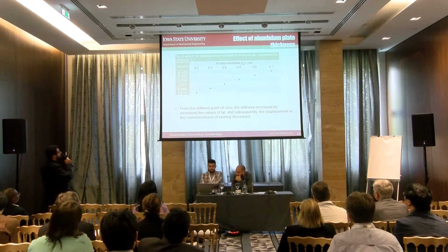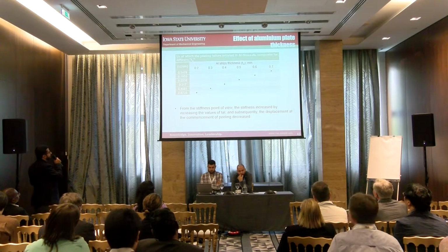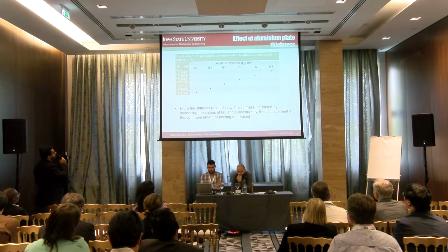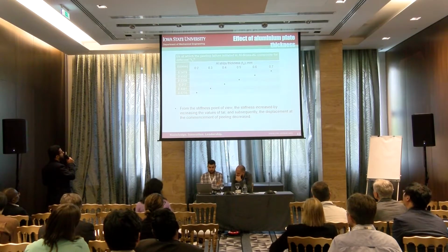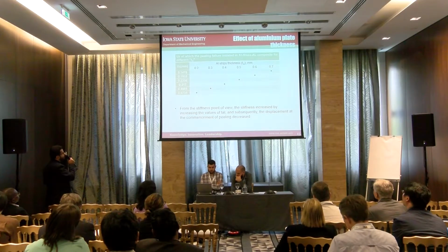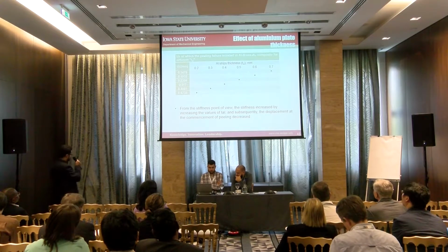Here we show just the UZ, which is the displacement when the crack is initiated, which is at the maximum load. From the stiffness point of view, the stiffness increased by increasing the value of the thickness, and subsequently the displacement at the commencement of the peeling is decreased.